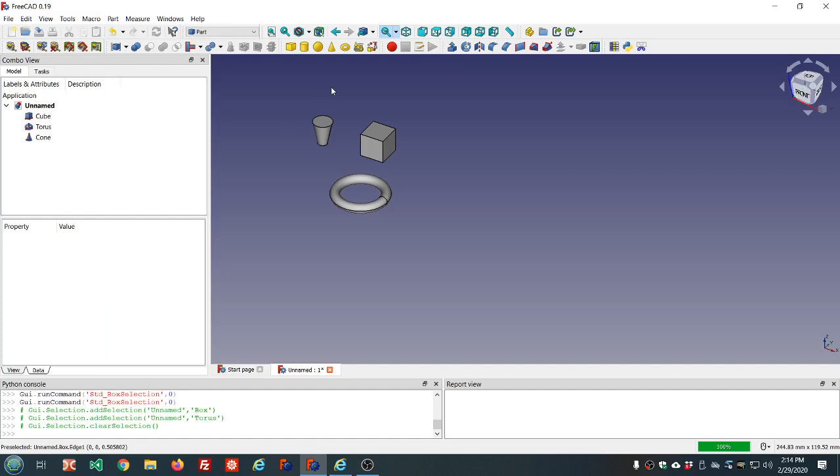A lot of people go on Thingiverse, download models to print out from other users, and those are usually in the form of a mesh STL object. And in order to work with that object in FreeCAD, you would need to convert it to a shape, and this can be done back and forth.